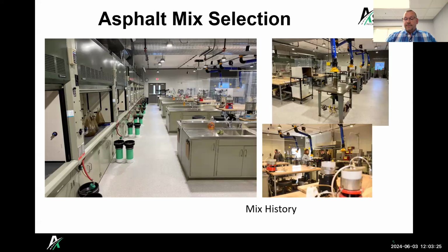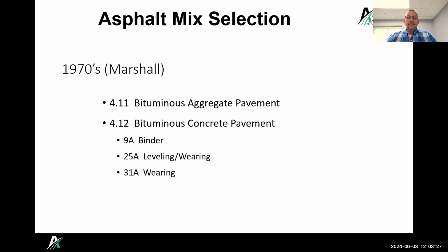So, mix history. We go back to the 70s. In the 70s, we used the 411 and 412 mixes. These were designed using the Marshall mix design methodology. These mixes were made and tested with certified aggregates and sand. Basically, MDOT tested and certified different aggregates and sand and told you how to proportion those and put together the mix design.